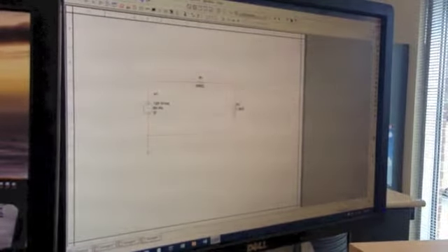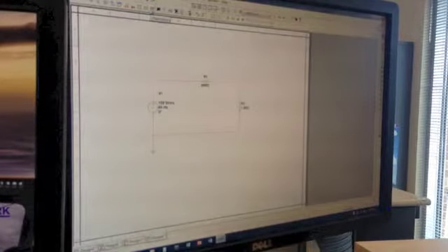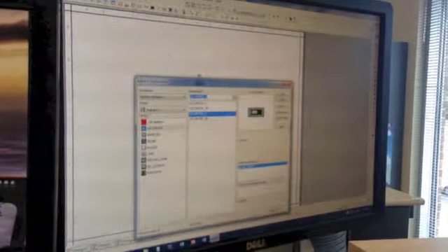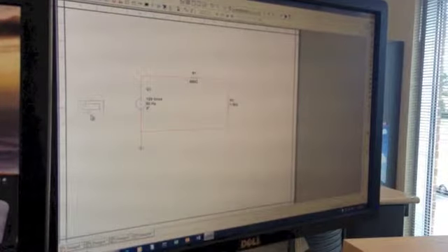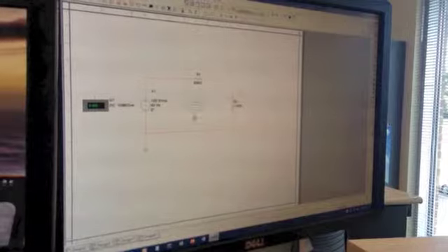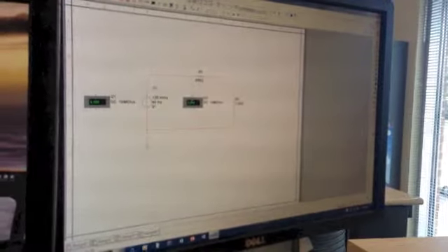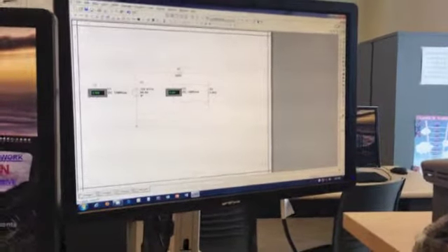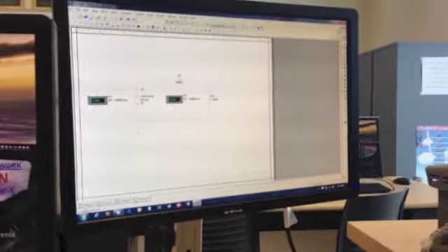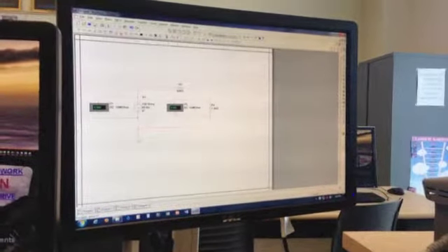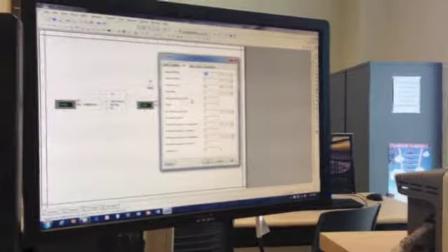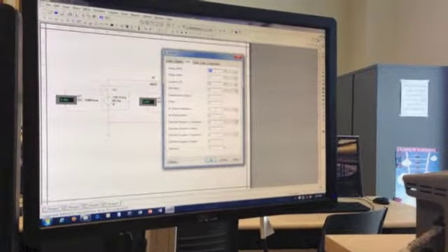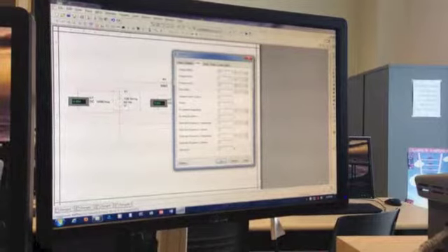And from there we can add our voltmeter so we can measure the RMS. So we'll add one next to the volt source and one for the R2 resistor. We'll connect the positive to the positive and the negative to the negative for R2, and the same thing for the volt source. And from there we'll open this AC source up, and the RMS that we got was 6 volts.